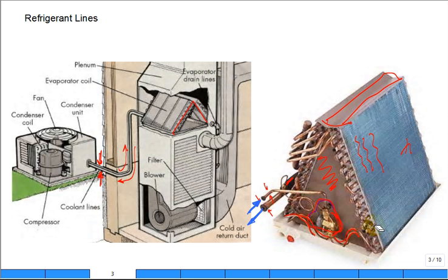Now, once they have 2 feeds on this side, they come up here, you can see 1, 2 coming out, true? 2 coming out. And on the other side, there's 2 coming out. And they collect in a larger suction line manifold. There's a little Z to it. It goes back and then it comes out this way. There. So there you go. There's the flow of refrigerant through that evaporator. It's called A coil because of its shape, and they're very common. Okay, the tray you can see collects the water, and there's little hookups to get the drain.